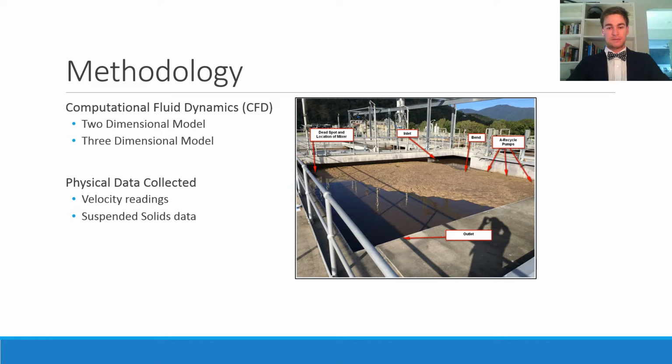The velocity probe uses an electromagnetic sensor to measure the velocity in one direction. For the extensive data collection, velocity readings were collected using the same equipment and taken in the same 4 locations. Readings were collected at the surface and at 1 meter intervals below the surface down to 3 meters. Readings were collected parallel and normal to the wall surface. The velocity was observed and the minimum and maximum readings recorded.